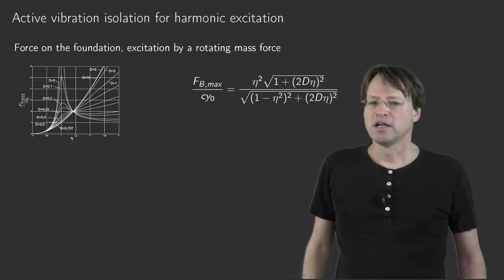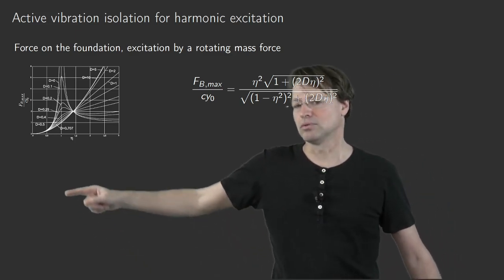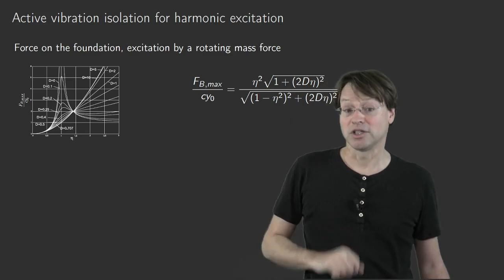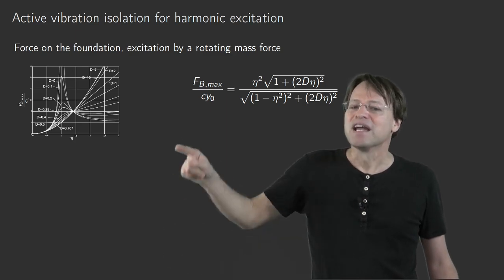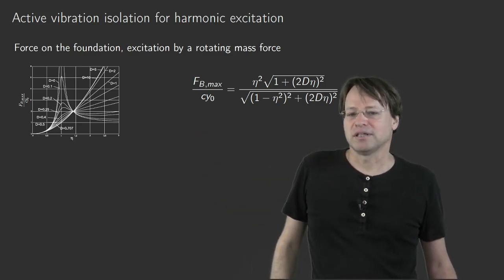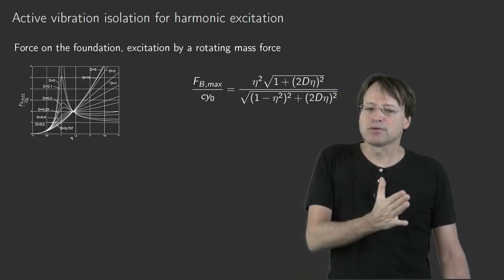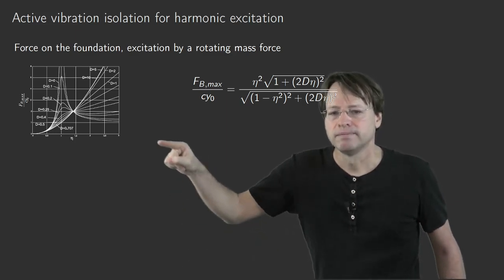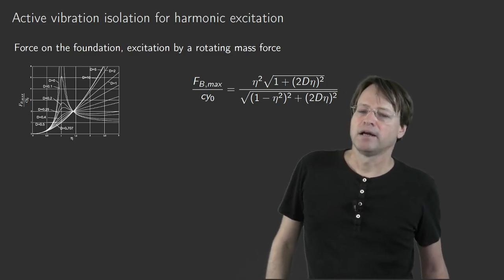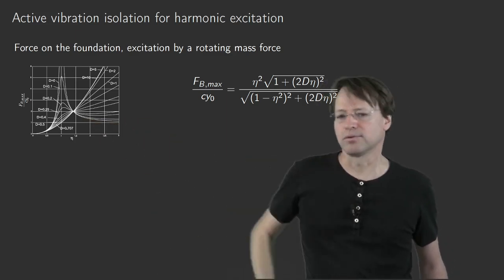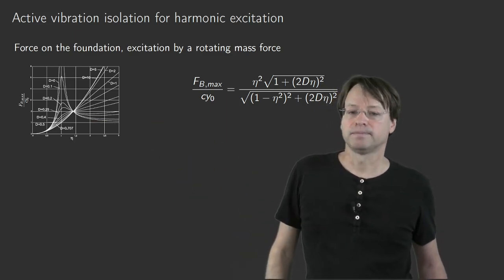And that answer is, if you are able to decrease the rotational speed of that imbalance to close to zero, and in general this is not possible because you want to have these rotations, then you will reduce that ground force. On the opposite end, if you have a high-speed rotor, a high-speed imbalance, then in some cases you are able to at least decrease that ratio again, compared to resonance, for example, but you are always larger than 1.